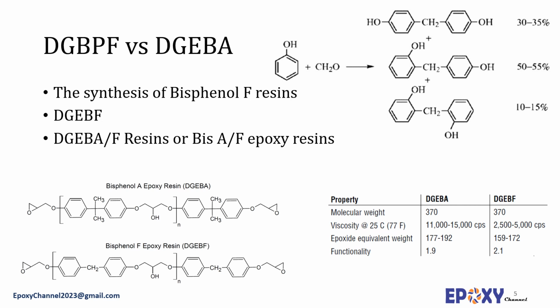This epoxy resin is also produced in a similar fashion, and if it is synthesized from phenol formaldehyde and epichlorohydrin, oxalic acid is used as a catalyst. Commonly, resins had an epoxide number of 0.65 to 0.68 mole per 100 grams and a viscosity of 1.3 pascal second.